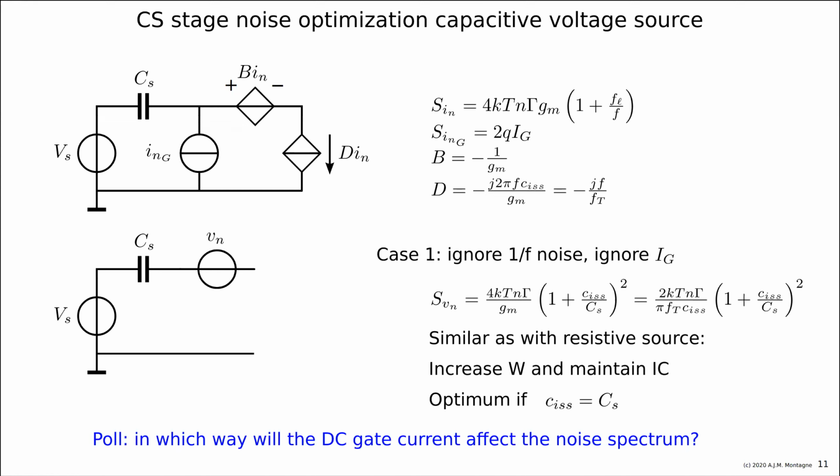So it increases with decreasing frequency with 6 dB per octave, because we just have a current flowing over a capacitor. So this current, this IG, sees, for low frequencies, a higher impedance, and it goes with the characteristic of the impedance, which is 6 dB per octave. That is the reason. It's not 1 over F noise.